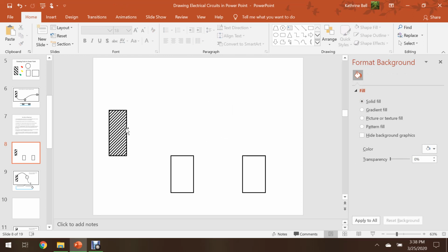All right, so I have my 2 device boxes for my parallel duplex receptacles. I want to run some electrical conductor. I can choose to come out the top, go over and down, or I can come out the bottom, over and up. I'm going to come out of the bottom of the service panel.